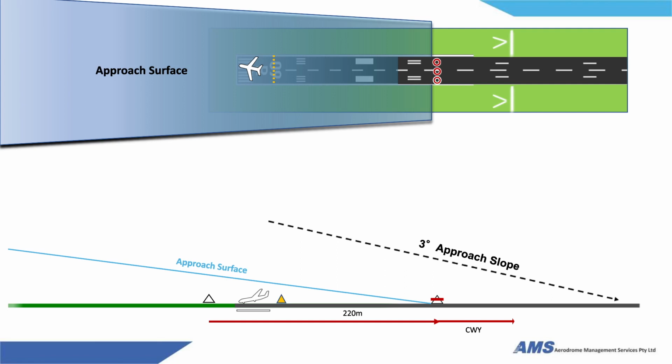Prior to reopening the runway for reduced length operations, we're going to have to calculate our new declared distances. Our new declared distances from the arrival end of the displaced threshold and also the departure end of the opposite reciprocal.